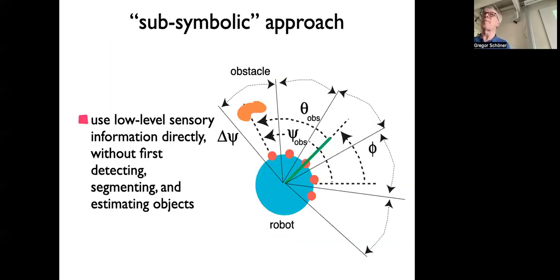So the example that we'll be looking at in more detail, the sensor was actually some uncalibrated distance sensor. It was an infrared light emitter and detector. That is, you would be sending an infrared light beam out, and that has some spread, and then just detect the amount of light of that frequency that is being reflected. And that reflectance would be somehow reflective of how far the surface is away from which it's reflected.